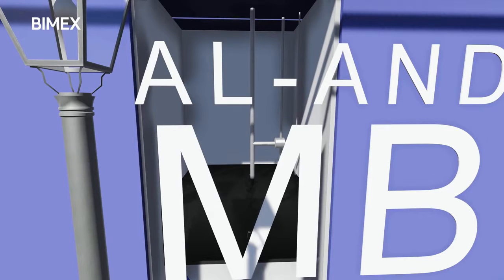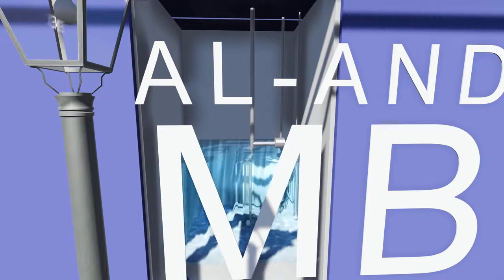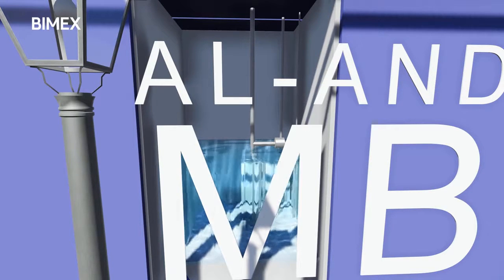Fluid from the MBBR aeration tank flows to the secondary clarifier. As the water flows upward, the sludge stays on the hopper plates and slides downward into the bottom of the hopper. It is in the clarifier that the fluid stream is separated into water and sludge. The mostly solid-free water rises to the top of the clarifier and out to the next treatment stage.